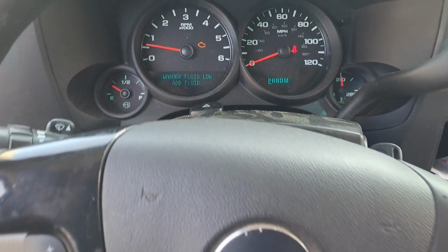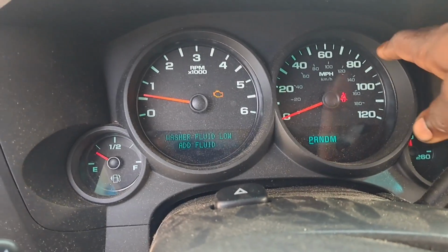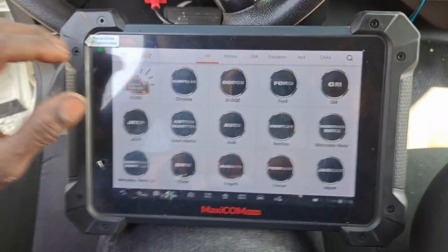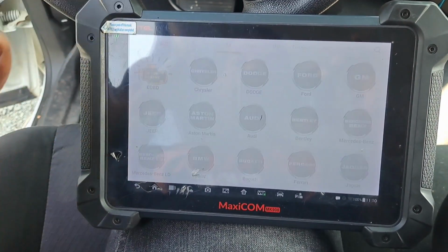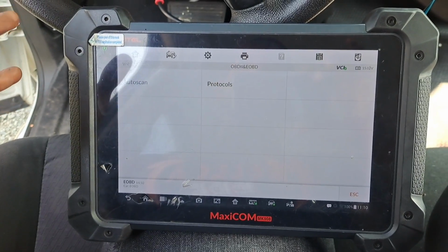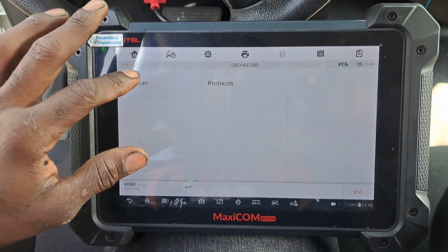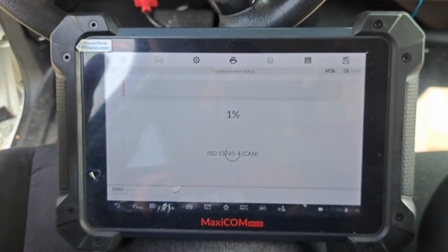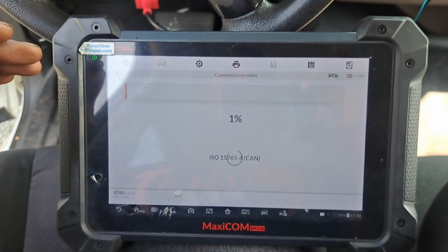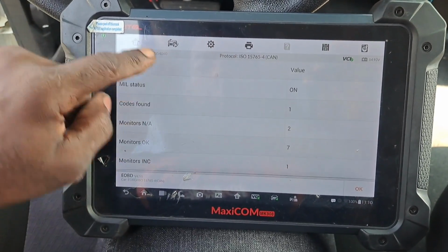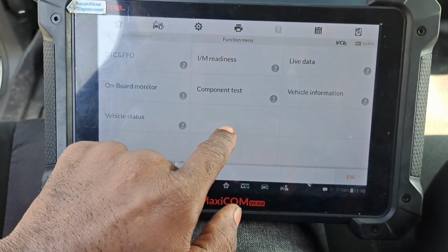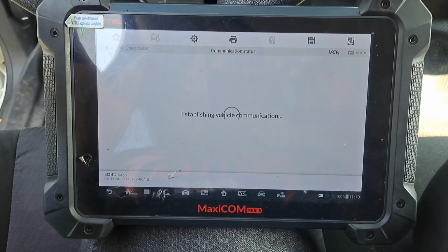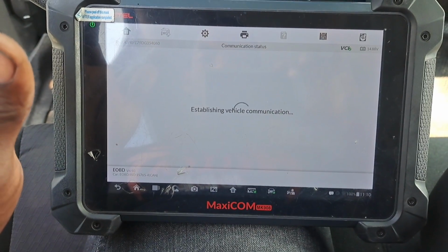So it's the next morning. I put several miles on this truck, about 30 miles, and the check engine light did pop back on. And mind you, yesterday, what I didn't document, I drove it 10 miles, no check engine light. Everything was fine. So 10 to 15, I want to say. Normally, the check engine light will pop on about 5 miles for that fuel imbalance. So I'm thinking, because I did a drive cycle and completed almost everything, we're probably dealing with evap. Hopefully.